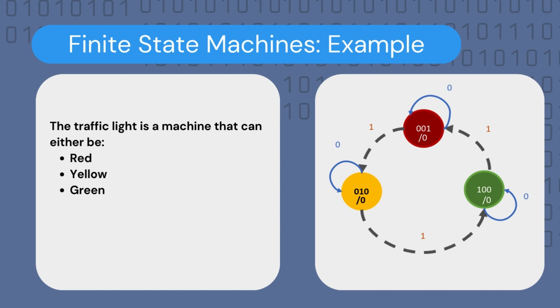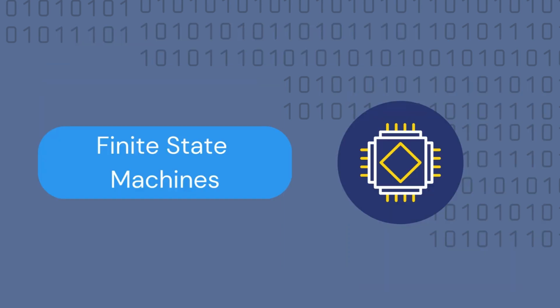Okay, so why should we use sequential statements to design a finite state machine? Why not use a concurrent statement? That is because we need memory to remember the current state in the next clock cycle for us to provide that decision of the transition of states. Not only that, but when we are designing a Mealy finite state machine, we don't only need to let the system memorize the current state, we need it to also remember the inputs for a time period so that it can implement the next transition correctly.